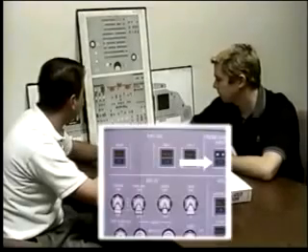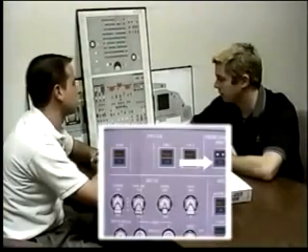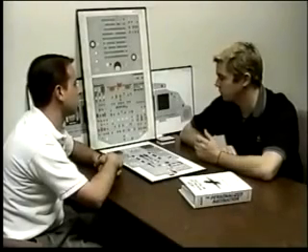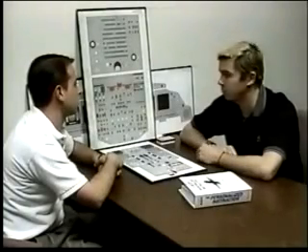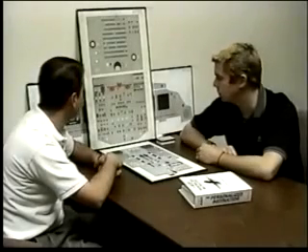When we're in flight, they shift to high, and then the TAT probe is also heated. What if I was to select the switch to on? Selecting the on only really does something between power on and the first engine start, and all I'm doing is commanding low power to the probes and window heat, with the exception, of course, of the TAT probe.